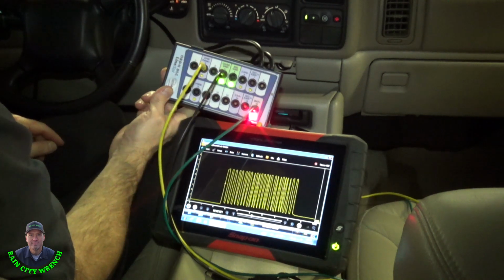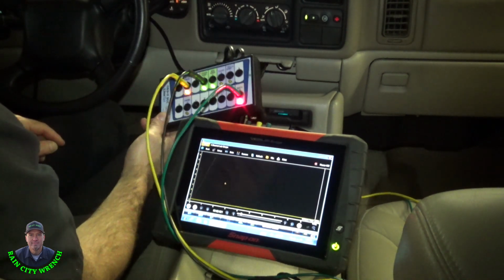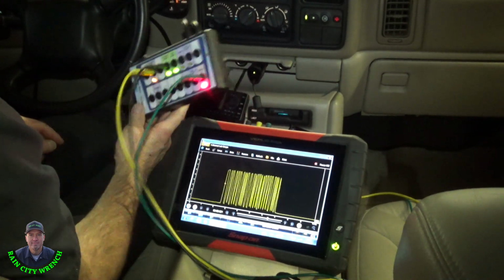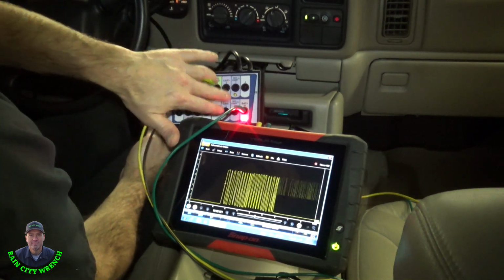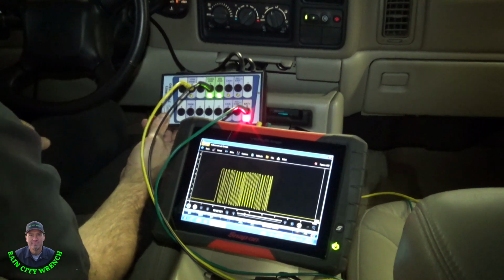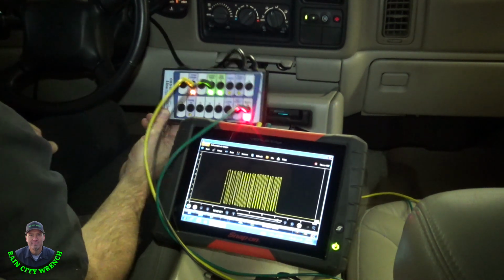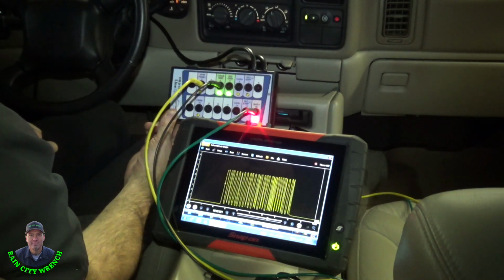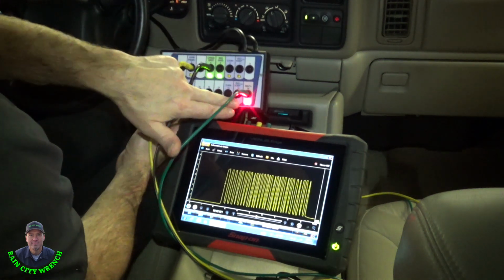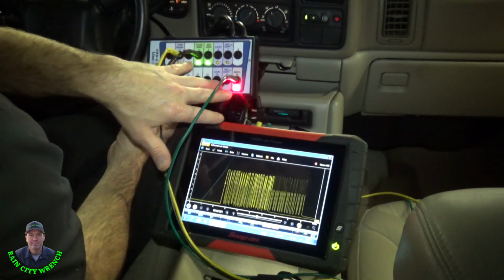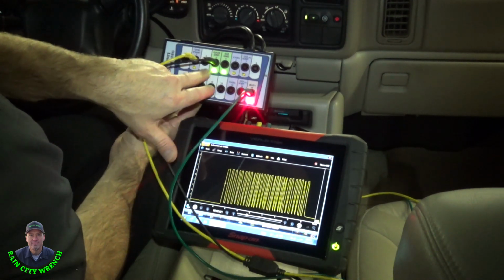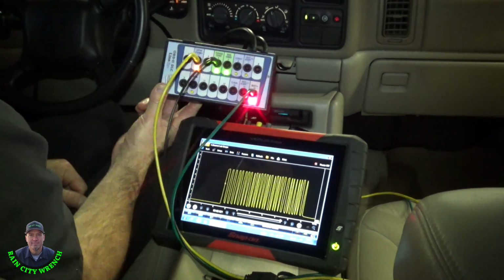But really cool checks you can do inside the vehicle. I mostly use this for looking at the ISO and CAN high and low. And what's nice about this breakout box too is you can quickly connect it in, and if your lights are on, these two green ones and the red one, most likely you've got a good power and good grounds.